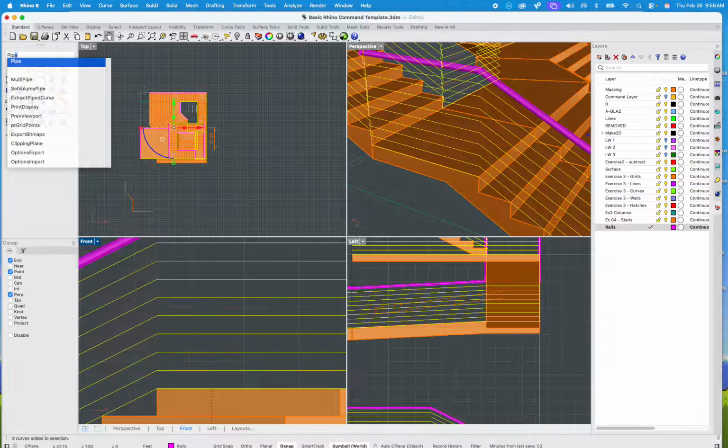You could sweep that, right? You get a very unique handrail immediately. Keep in mind, we're not going to actually make the handrails, so you can get as fancy with those as you like. Or many handrails are often like this, somewhat rounded. Now, of course, I'm showing you the section view, right? So, just kind of draw that out. But you'd absolutely take this as your profile for that sweep, right? And then, of course, the sweep would follow the path. In my case, I'm just going to pipe them for the sake of tutorial.